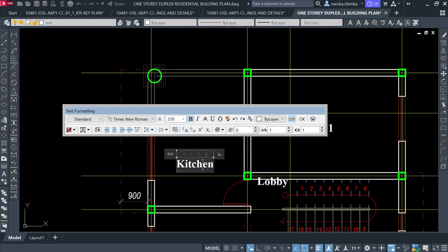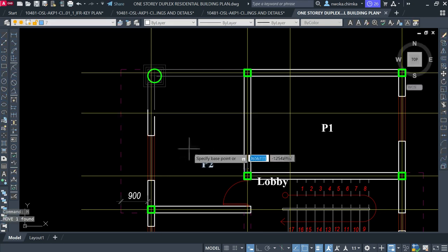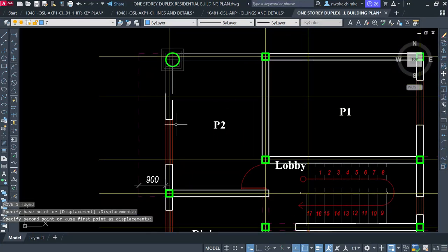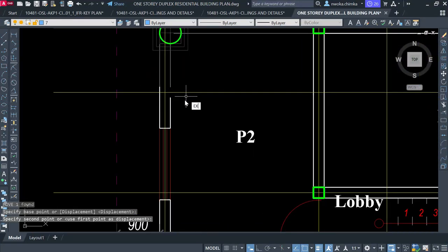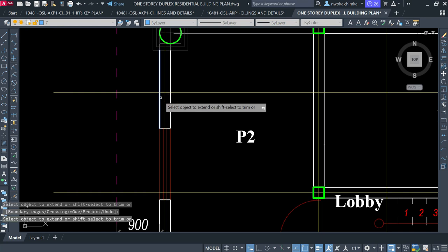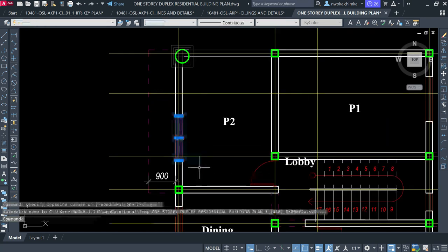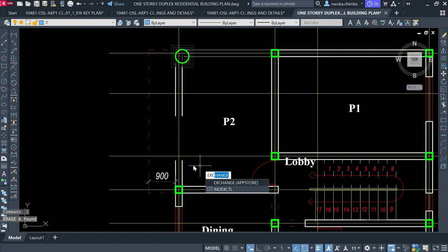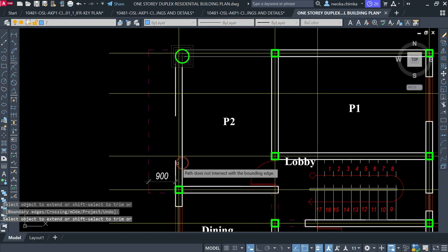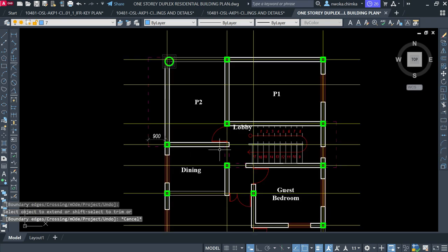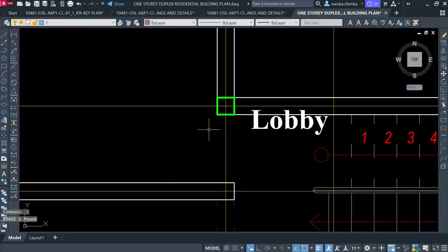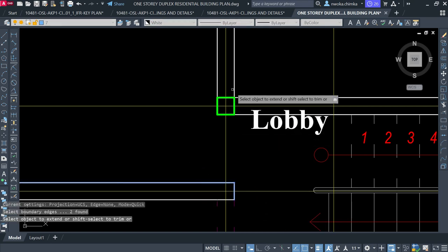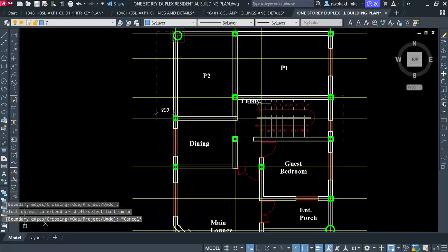So I'll call here panel 2 because I have checked that they are within that rule. I can choose to extend my line just to cover this up and cover this up. Remove this window symbol and then cover this up. I can choose to remove this door now because I've already positioned all my columns, and then extend this line into this place, into here and into here.